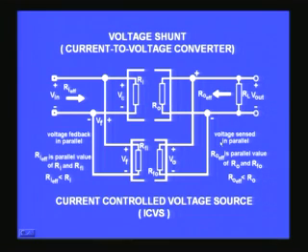So that is what is shown here. Voltage sensed in parallel, so the effective output resistance is the parallel value of R output and RF output, where RF output is the resistance of the feedback network, Thevenin's resistance as seen from the output side. So R out effective will be less than the previous RO without feedback. So that is a consequence of this feedback.